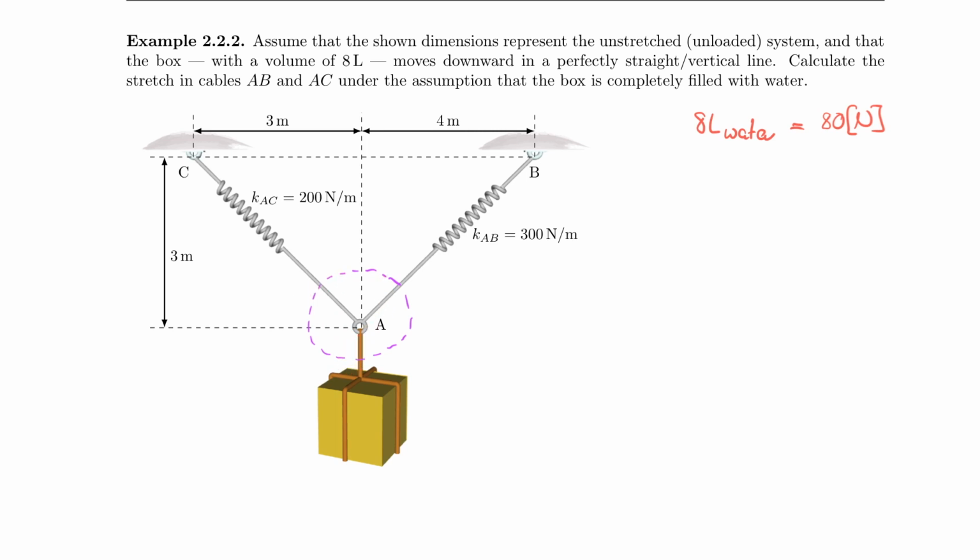And why is that important to understand? Because we have the sum of the forces in x is equal to 0, and we have the sum of the forces in y is equal to 0. And that means I have 2 equilibrium conditions. And therefore, I can only solve 2 unknowns at a time, because if I have 2 equations, I cannot solve more than 2 unknowns. Or likewise, if I had 3 unknowns, I could not solve that with 2 conditions. And that is why when you draw free body diagrams and when you cut the system, you always have to make sure that you only cut through 2 unknowns.